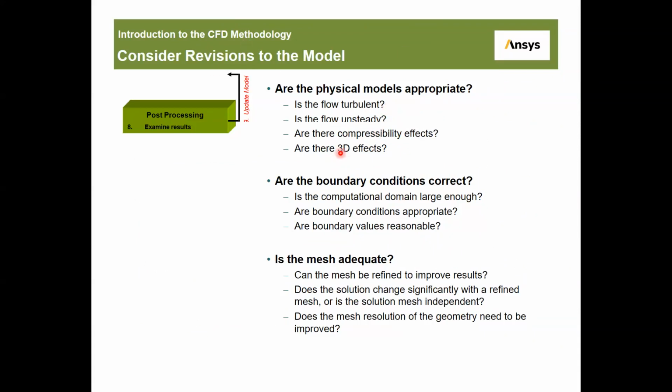Is our boundary condition okay? Is the mesh correct, is it enough? Okay, if we use, let's say, 1000 mesh compared to 2000 mesh, make sure our result does not change.